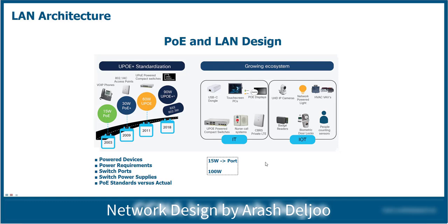Because of that, you should consider the total PoE or power over Ethernet requirement, and after that you should choose the switch with compatibility with the total PoE requirement that you have.